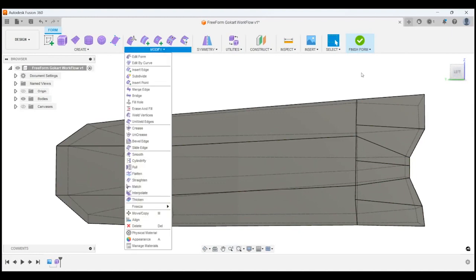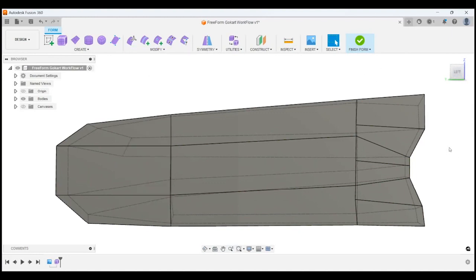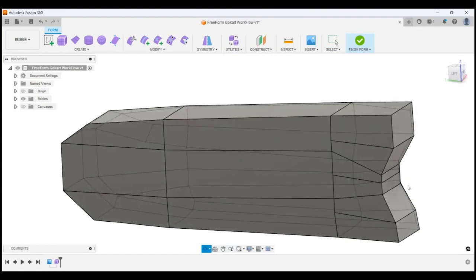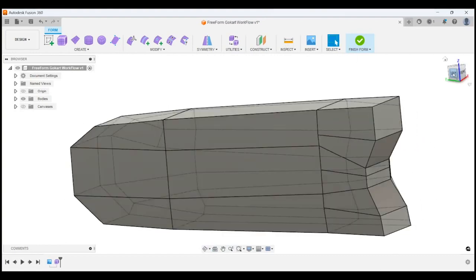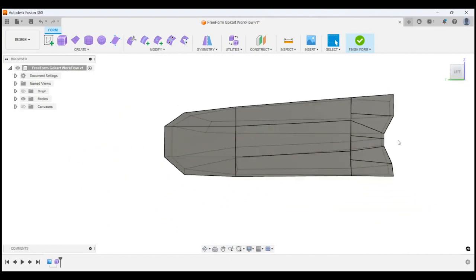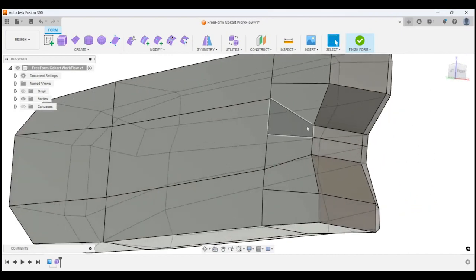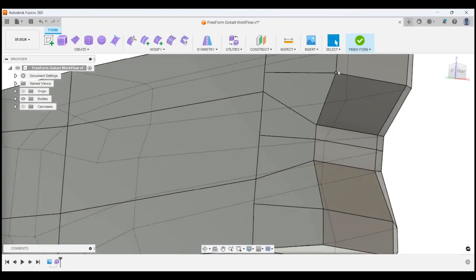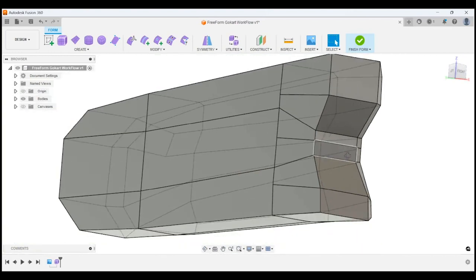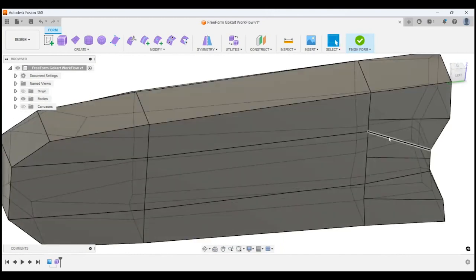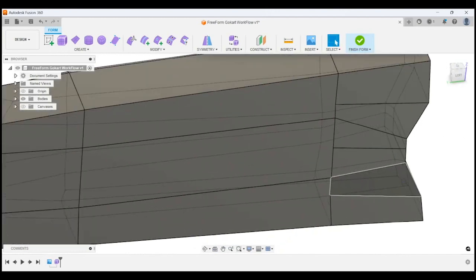So you could chain select that entire edge of faces we made and weld them to this, and generally it will meet them up because this is actually a fairly simple geometry, but sometimes it doesn't, and sometimes you get vertices where the vertex here would be welded to this point, and the vertex that should be on here would be welded at this point. So you get this twisting effect, and it creates a kink in the geometry that's actually hard to see even in box display.